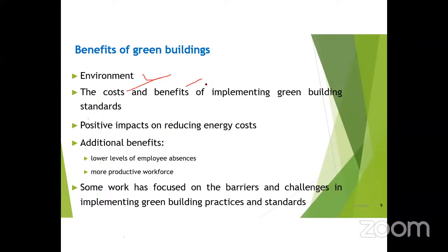Green building generates lesser pollution both during construction as well as in use. मी तुम्हाला म्हटलं construction मध्ये less आहे. Why? You are sprinkling the water whenever you are going for the site. Construction मध्ये green building मध्ये construction management plays an important role. Whenever there is construction on site, if your site layout is such that all the material and equipment are nearby, that means you are giving less disturbance to the other areas, less site disturbance, then your air pollution is less.